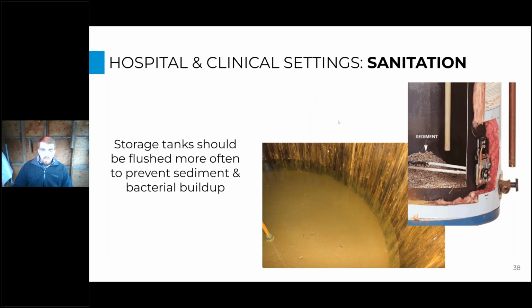One more thing we'll need to think about with storage, especially in a hospital setting, is sanitation. So we need to make sure that we develop a maintenance schedule for the building maintenance to flush these tanks regularly and make sure that there isn't any sediment build up in the bottom of the tank that will harbor bacterial growth. And this flush is really easy, because if you say you plumb this drain to a floor drain in the mechanical room, then once you open this drain pipe, you don't have to drain the tanks completely. You can actually keep the water supply to the tanks open, and it will just basically shoot water out this drain and keep replenishing it through the cold water makeup setup that's already there. So all you have to do is just open this drain up, and it'll flush all the sediment out on a regular basis, and that's really good to maintain sanitary tanks.